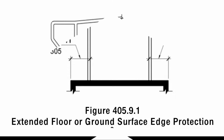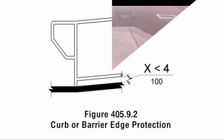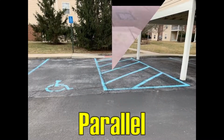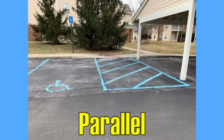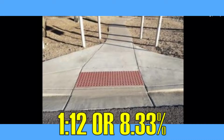It can be a curb or barrier that prevents the passage of a 4-inch diameter sphere where any portion of the sphere is within 4 inches of the finished floor or ground surface. Curb ramps shall be provided anywhere an accessible route crosses a curb. The slope of the curb ramp cannot exceed 1 in 12 or 8.33%.